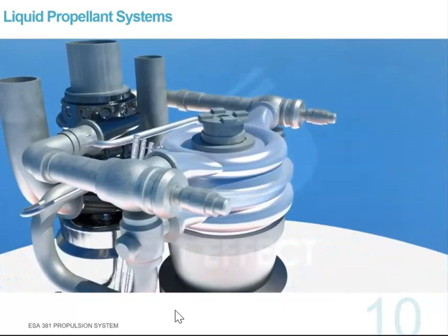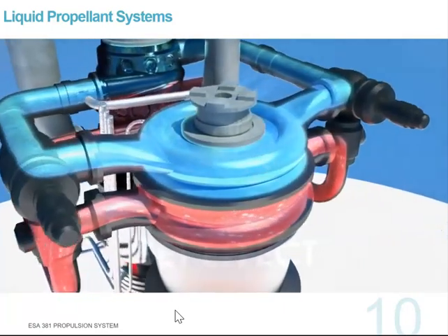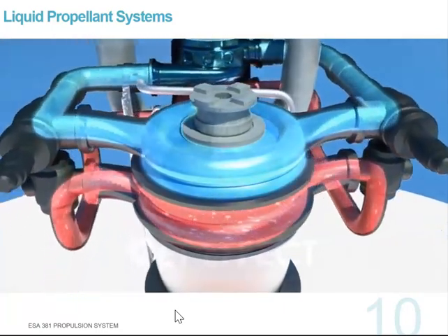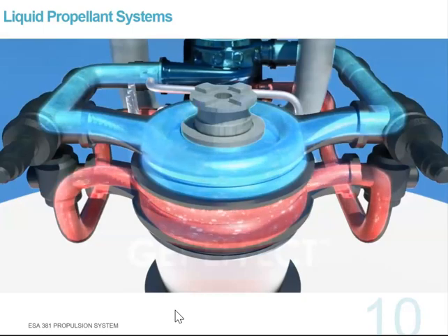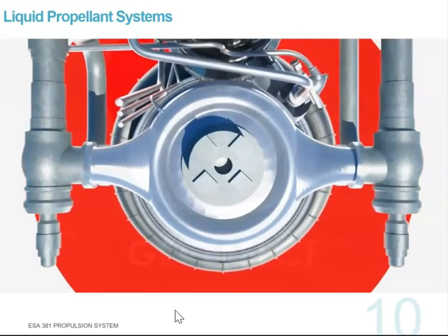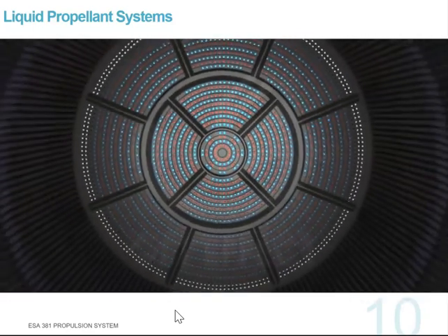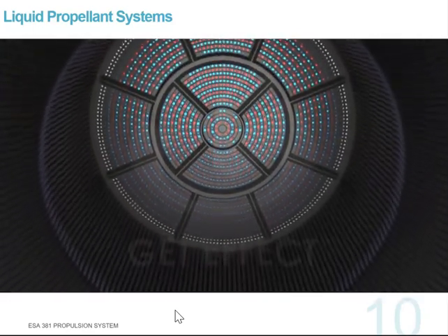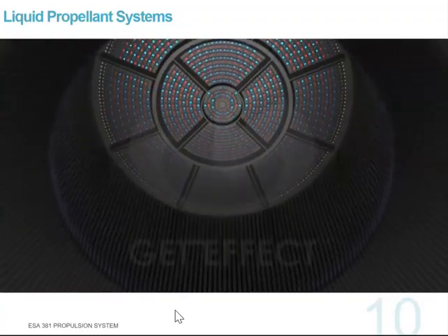Exiting the pumps, liquid oxygen and RP1 propellant were introduced at high pressure into the liquid oxygen dome, and RP1 manifold. From there they were forced through the injectors, and sprayed at the top of the combustion chamber, below the injector plate, creating an extremely explosive mist.